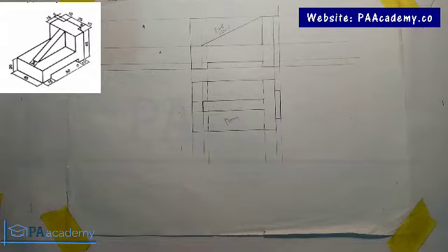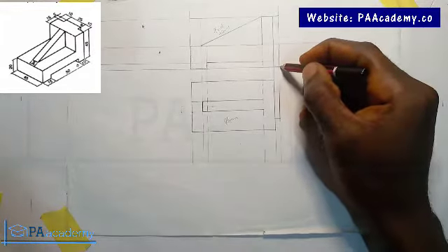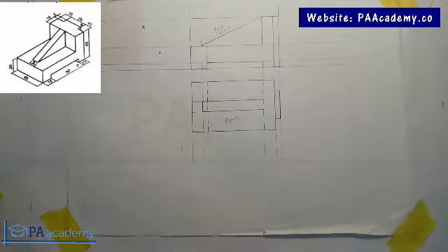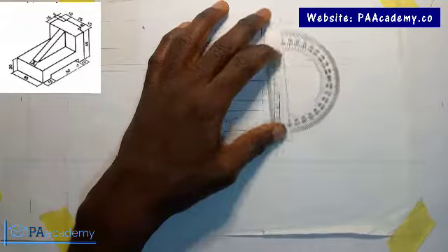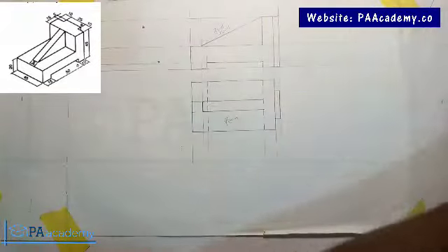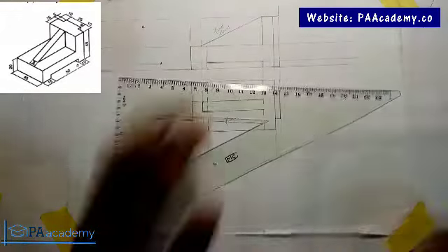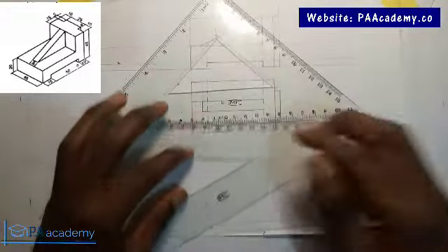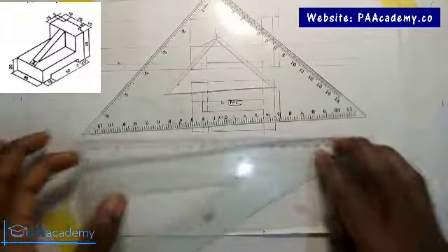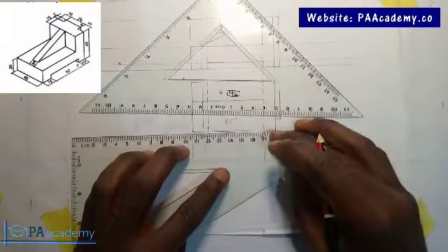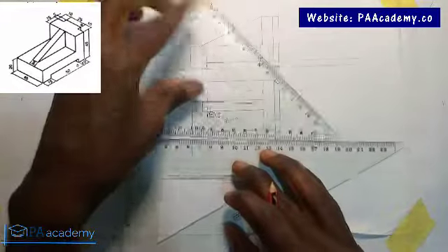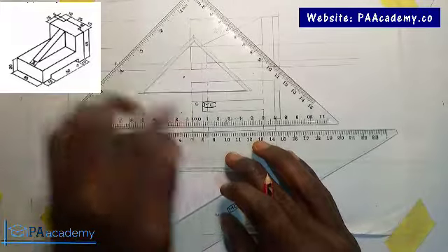All right, now the next is to draw the angle of 45 degrees. So like I explained earlier, from this point here, you draw an angle of 45 degrees. You can decide to use your 45 degree set square too, even if you do not see your protractor. Let's do this. So if your protractor is not handy, you can also use your 45 degree set square.